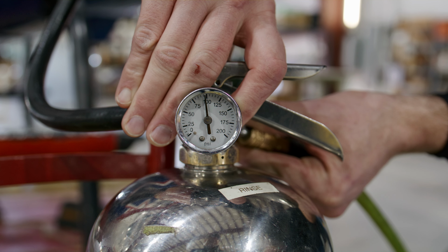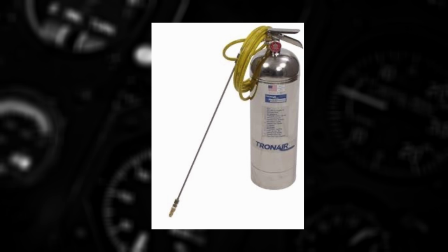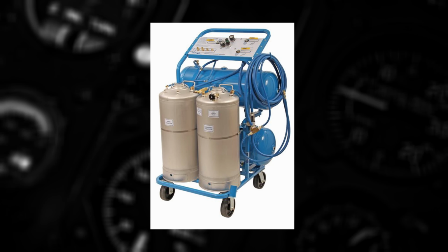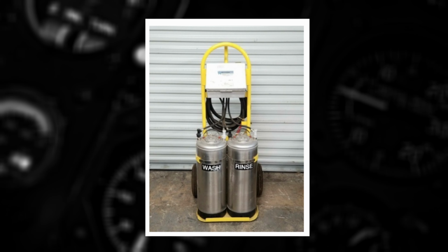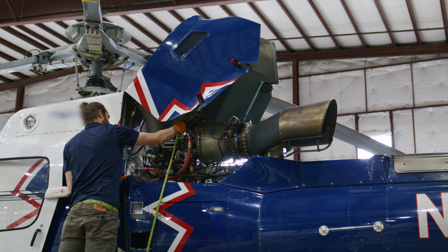Operators of our engines have many different delivery methods for injecting the cleaning and rinsing liquids, from a simple portable spray tank with a handheld wand directed at the inlet, to a heated, electric pump-equipped 2-tank wash kit connected to the airframe fitting. However, more often than not, these methods are used without regard to the prescribed quantities or flow rates specified in the maintenance manual, which has several potential risks.